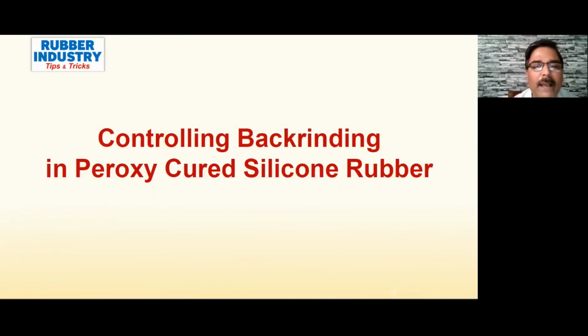Next is controlling backrinding in peroxide cured silicone rubber. Silicone rubber in a peroxide system, during compression or even in 3-plate or 4-plate transfer molds, generates backrinding across the flash line. So we need to select a suitable grade, preferably with low thermal expansion.